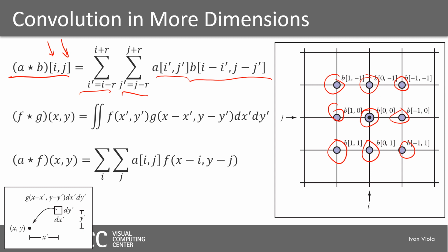So we have a two-dimensional input signal and a two-dimensional kernel, where the values of the kernel are, again, for smoothing filters, maybe the value at B00 will be highest, and for the samples which are closer to it, B10 will be higher than, for example, at the ones which are on the diagonal.